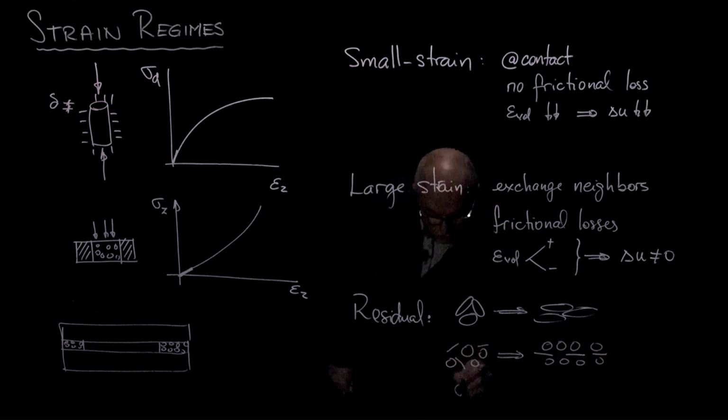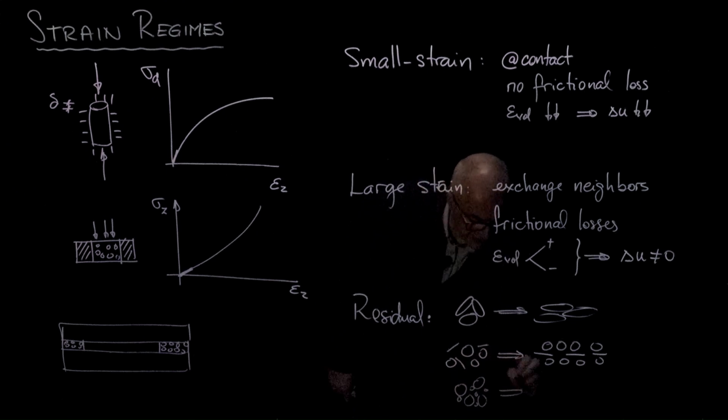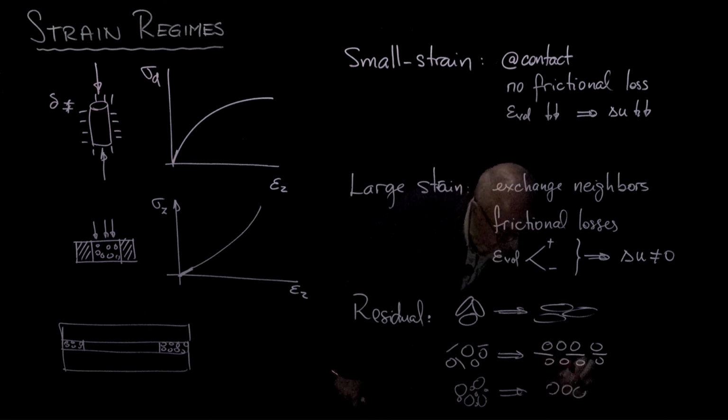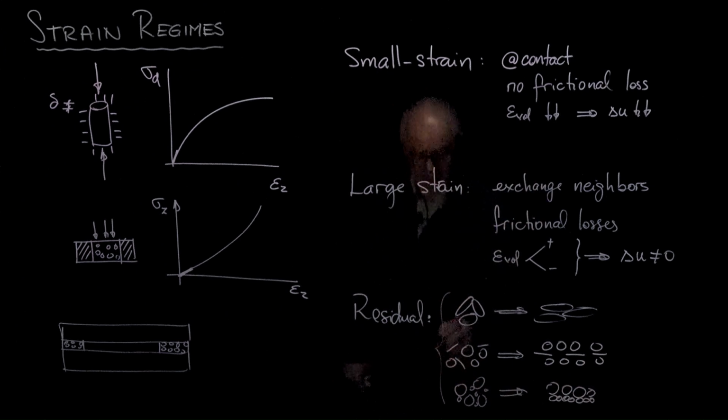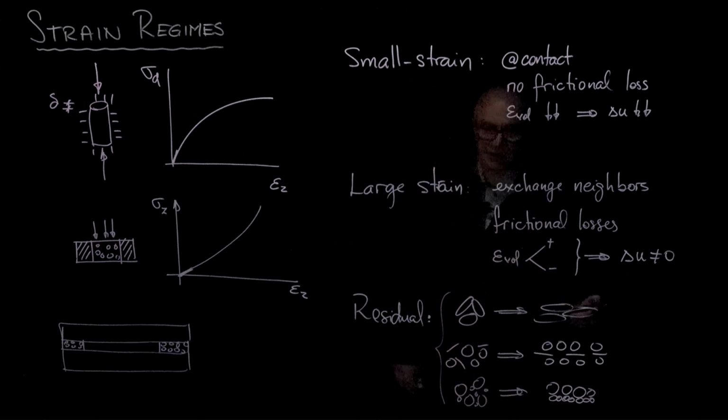And if there are coarse and fine grains, they tend to segregate, and the coarse grains will tend to ride on a bed of smaller grains. So in the residual regime, there is particle alignment, particle segregation, and the segregation could be of plated particles or segregation due to size.